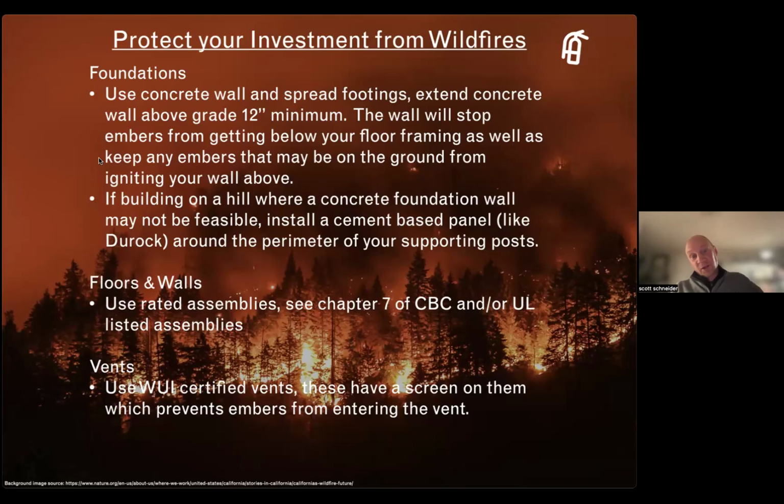And if you are on a hill and a wall may not be feasible, you can build a fire rated wall down below the floor framing, or you can use something like Durarock and place that all around the perimeter of the posts.